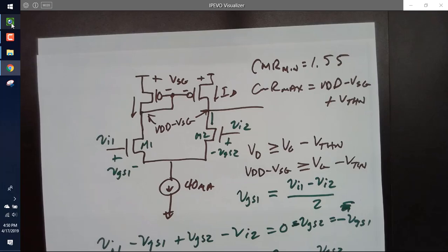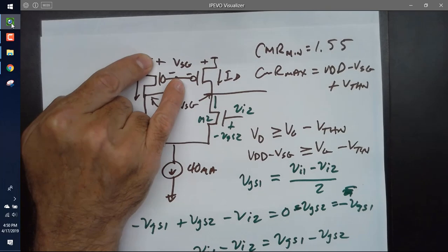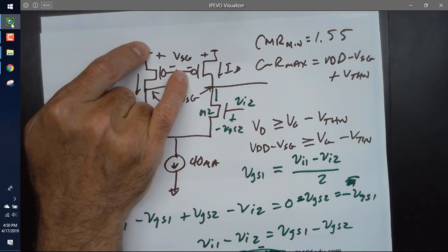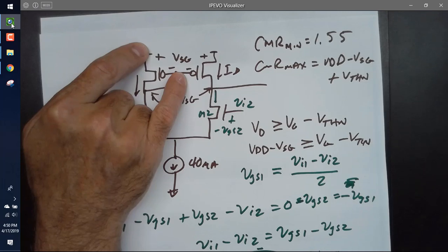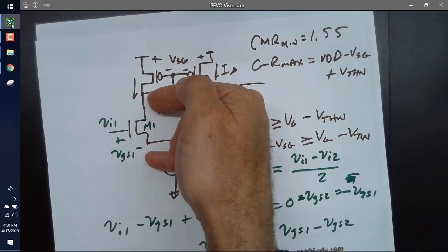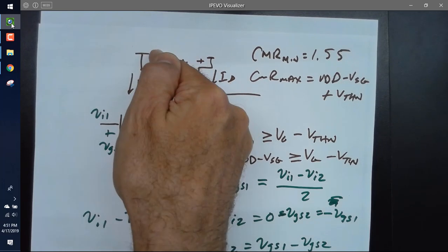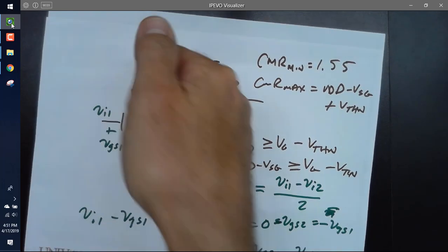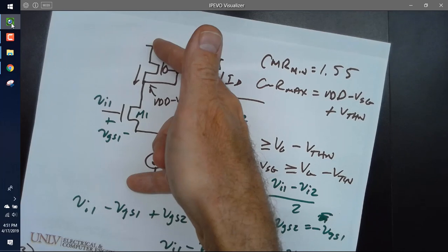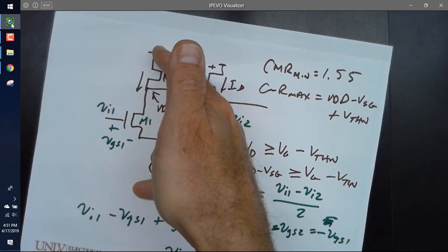So if I look at this right here, you notice that with the sizes that I have, this is going to eat 1.15 volts by itself. Does everybody see that? Then with the device sizes that I have, I need another 0.25 up there. So now just from here to here, we're already up to 1.3, 1.4 volts. Then if I have a simple current mirror here, I have another 0.25, so just with that I'm already down to 1.6 volts, just to be on the edge. So I want to make sure I have a larger margin.